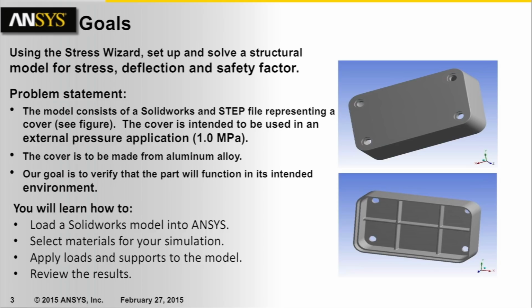What the model consists of is SolidWorks and step files representing a cover, and this cover is intended to be used in an external pressure application where we apply 1 megapascal. It's made out of aluminum alloy, and what we want to do is verify that the part will actually function in its intended environment and have a sufficient safety factor.